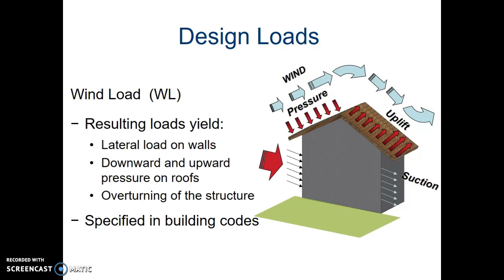These figures are referred to in the exposure category sections of building codes. For low-rise buildings, the wind load can be transferred through shear walls, like masonry walls in an elevator shaft, and an exterior masonry wall or steel bracing in the structural frame.